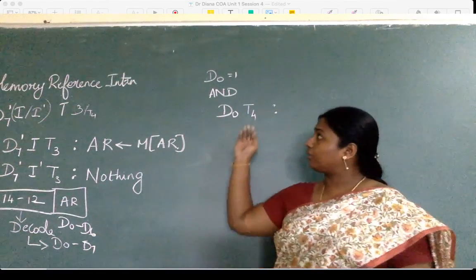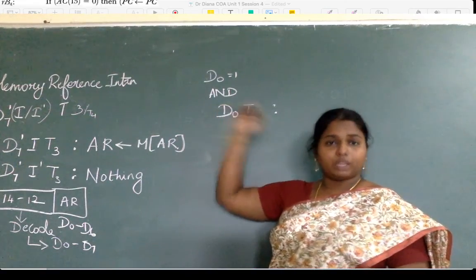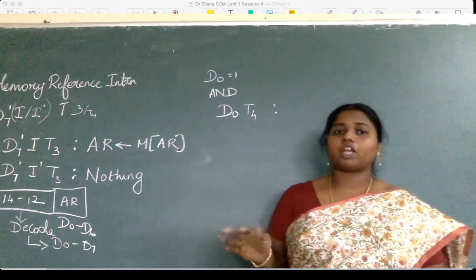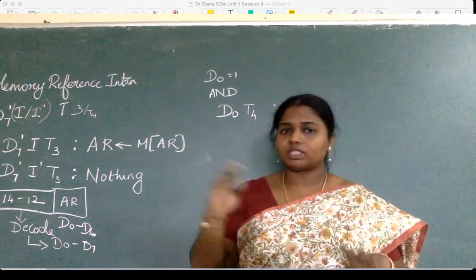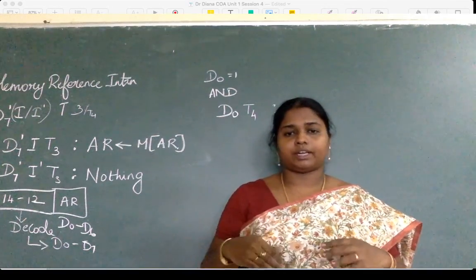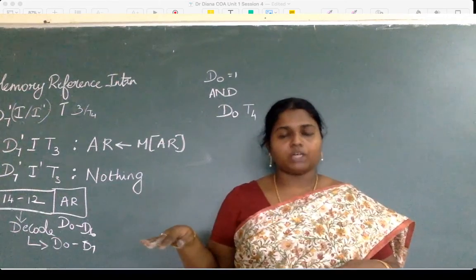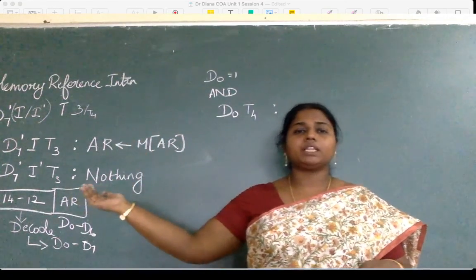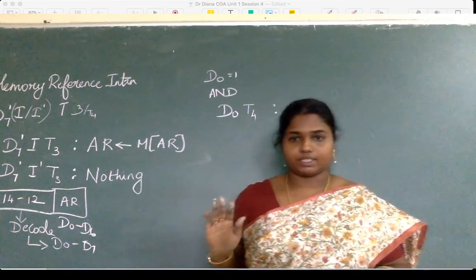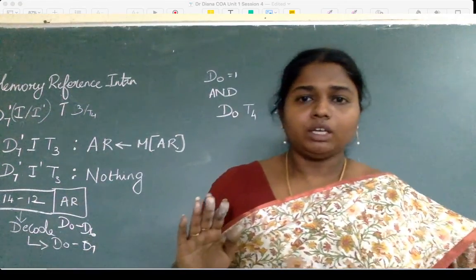Now because I have to do an AND operation with the content of the accumulator, I cannot bring it into the accumulator because it will overwrite the data content of the accumulator. To avoid that, I have to bring the data and put it inside the data register.